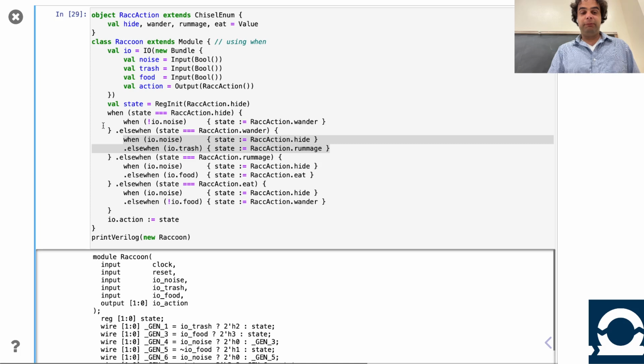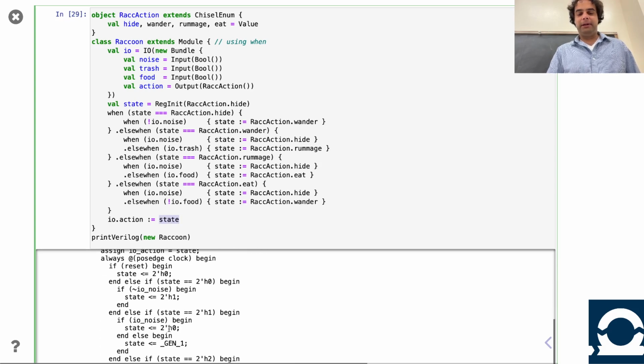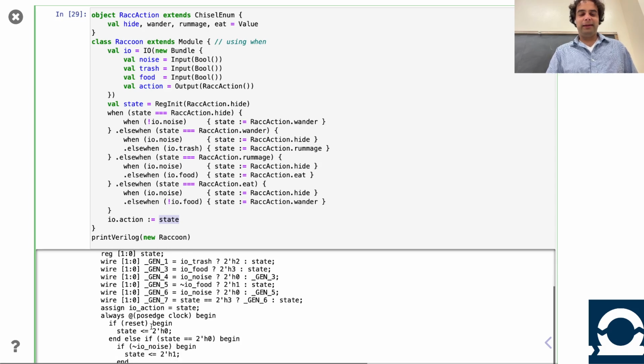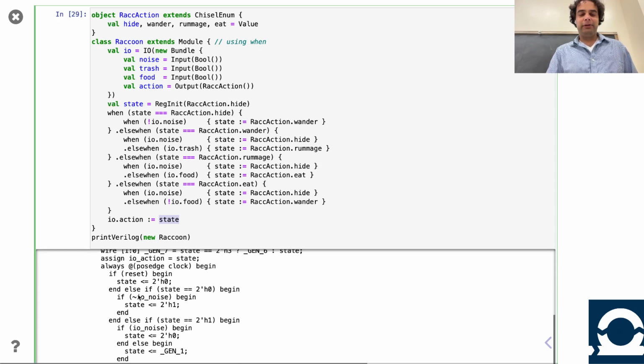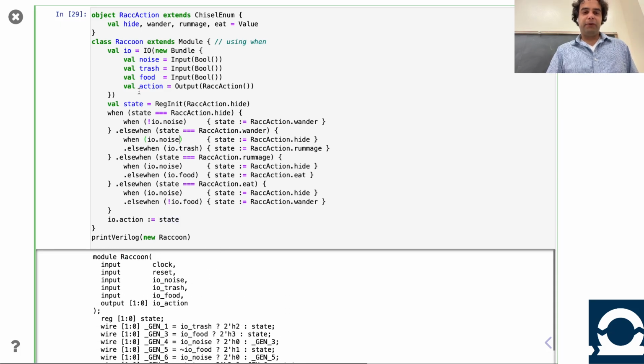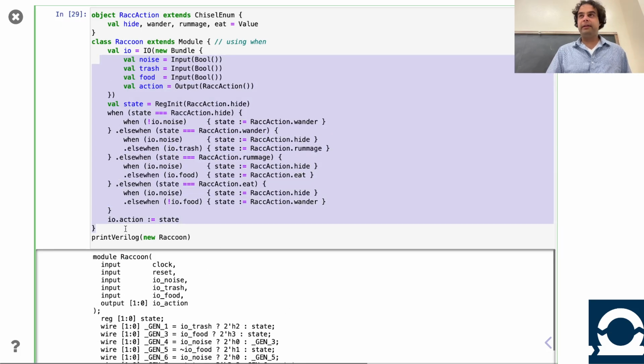But you can see how this fits together. Nested whens and else whens is totally reasonable code. I did a little bit of extra spacing to make things easier to read. Of course, the output is about as registers. Yes, there's Verilog down here, but you can see it's a lot. The Verilog is always kind of internal muxes. That's how it gets mapped out. And there are, of course, the default settings of the registers, but that's not important. I'd focus on this. Other questions on this state machine implementation?